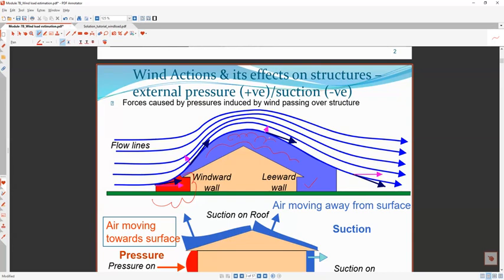Also there's an increase in the velocity here, because you can see the distance between the streamlines has become reduced, meaning there's an increase in the velocity, because it is now passing through a smaller area compared to what it was before. That's why I get the increase in velocity there. You can look at this cross section and that cross section. So we can see the separation of the boundary layer and the eddies, and then it is again going back to the original flow.